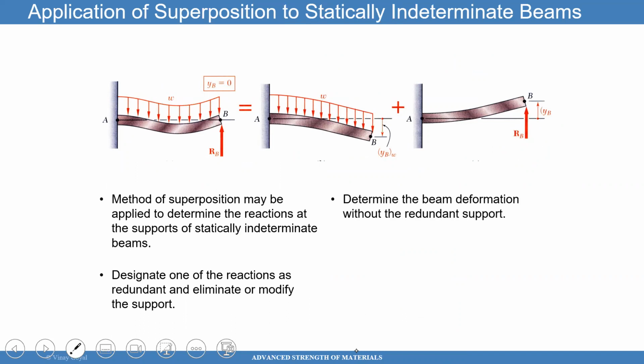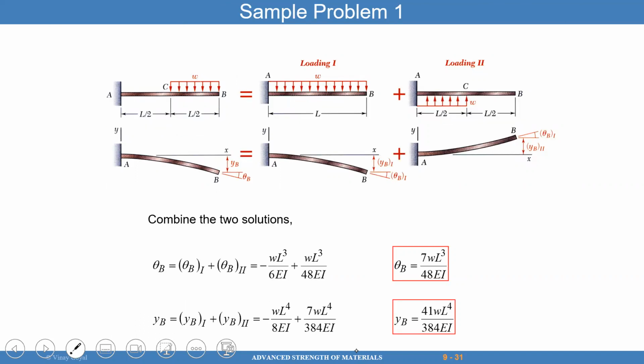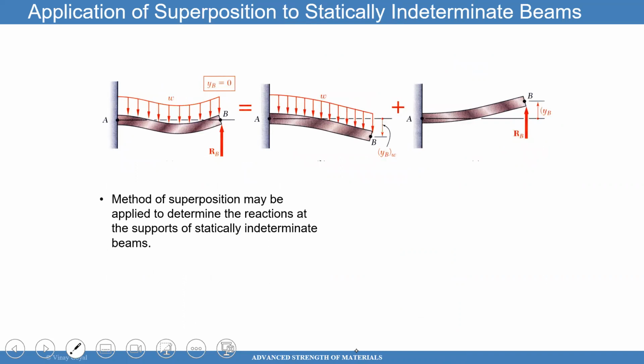Yeah, so there you go. Here's another problem. That's application of superposition for indeterminate beams. So say that this here was fixed, like pinned. I can remove that pin and apply a load, so that you can break this problem into two now.